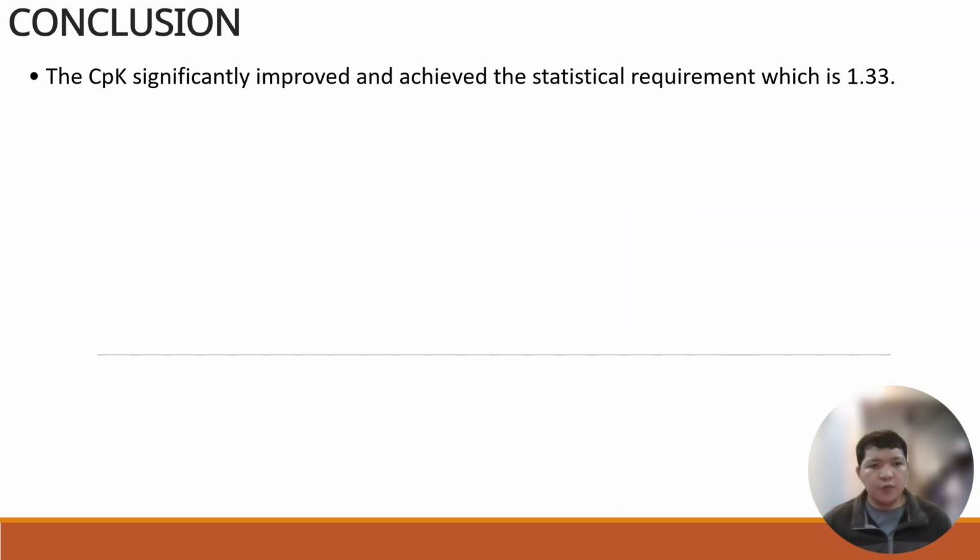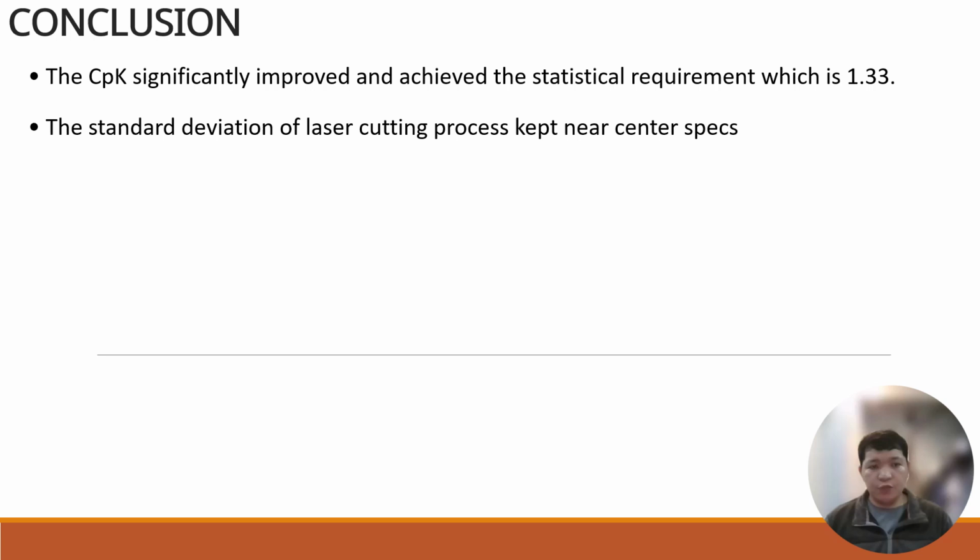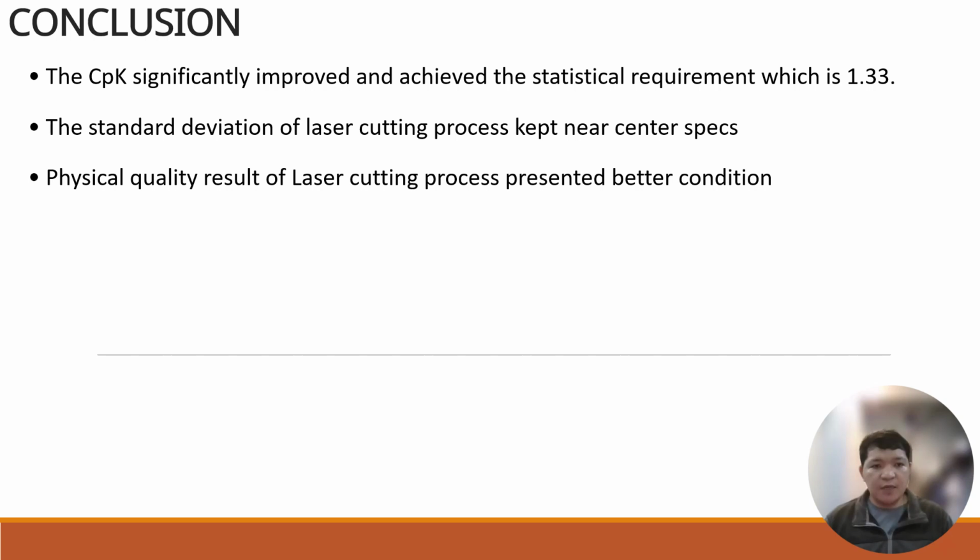So for our conclusion, the CPK significantly improved and achieved the statistical requirement, which is 1.33. Also, the standard deviation of the laser cutting process kept near center specs, and the physical quality result of the laser process presented is in a better condition.